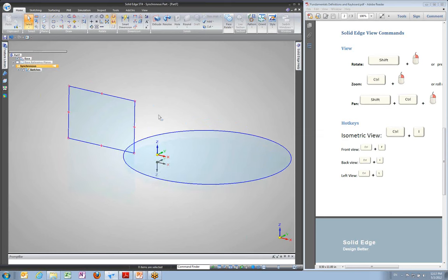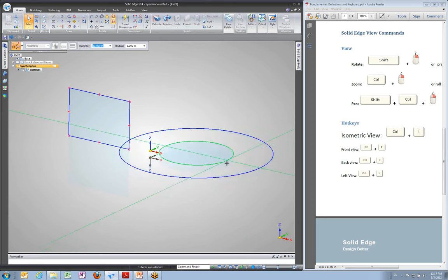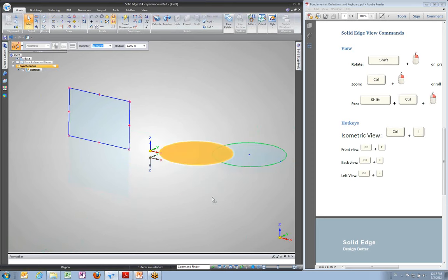We're not there yet. The other thing you can do is click on just the edge of the sketch. And when you do that, you're going to get handle points. Now, a circle has two handle points. One of them is the center point, which is right here. The other one is this handle point, which will be somewhere along the radius. And basically, clicking and dragging these will allow you to either resize or move that piece of sketch geometry. Similarly, if I click on a line, I get two handle points, one on each corner. I've also got the line itself, which when you click and drag will allow you to move the geometry normal to that line. So you should see your cursor turn into a little X or cross, and that indicates that you're over a key point. But the point is you want to click the line first to wake up those key points.